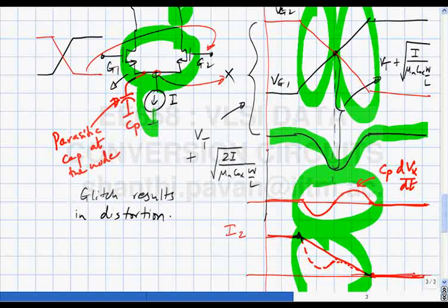So the cascode is doing two things. One, it is enhancing the DC output impedance. Two, it is also enhancing the AC output impedance. The AC output impedance earlier was simply the big capacitance of the lower transistor's drain. Now because of the cascode, which can be made much smaller than the lower transistor because the mismatch in the cascode is not an issue, the capacitance at the drain of the cascode is also much smaller than it would be if the cascode wasn't there. That also helps greatly in reducing distortion.